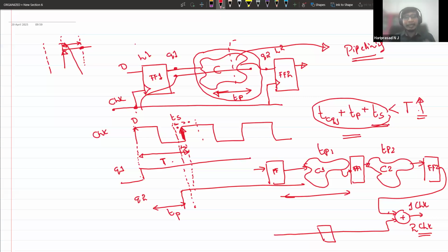In FPGA, we rarely see the hold violation because the whole architecture is fixed. But in case you see it, it is very tricky to handle the hold violation. It is not straightforward as in ASIC. Usually in ASIC, people say I am going to put some buffers. But here, one thing I can do is go for synthesis strategies. Especially in highly congested designs, you start seeing the hold violation, because these flops are fixed. You have not designed them. So this FPGA hold design is fixed.